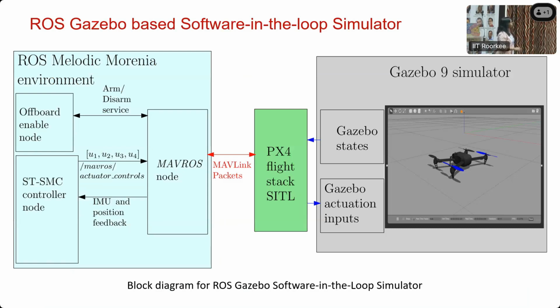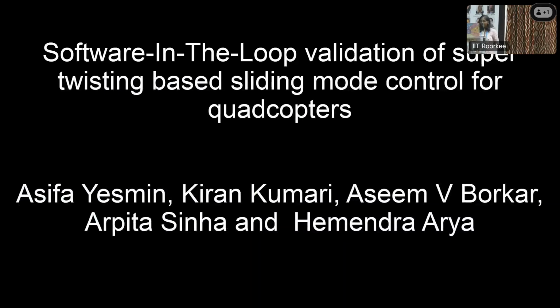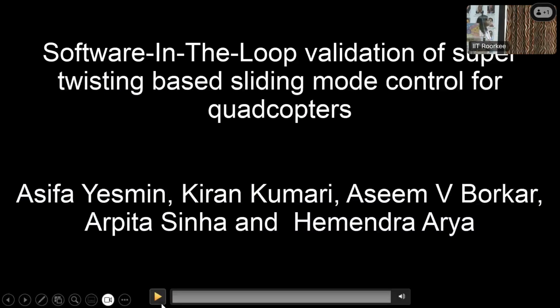Here, because of this PX4 flight stack, normally it comes with the PID control, that you can use in a mode by which the PID control will be tuned. We have disabled that, and we have done the whole control ourselves. That's why the controller which we have given is totally sliding mode based. We have not used PID control at all over here. So I would like to show this video of this implementation.